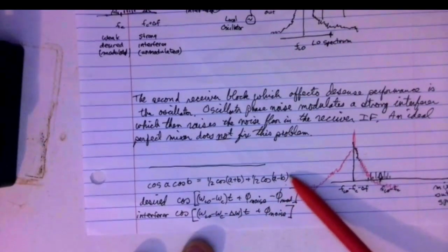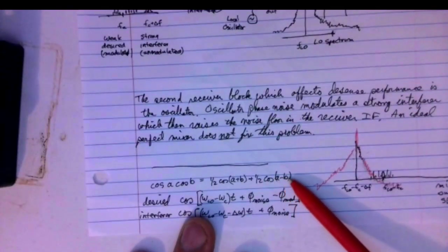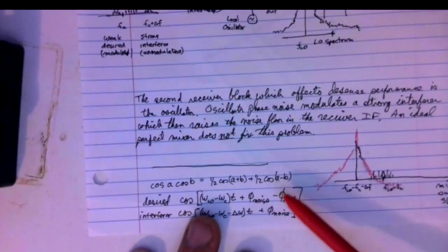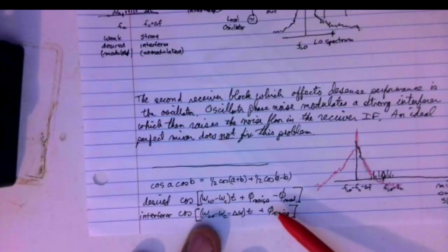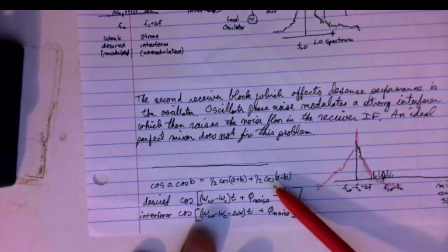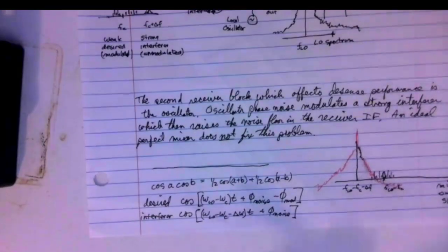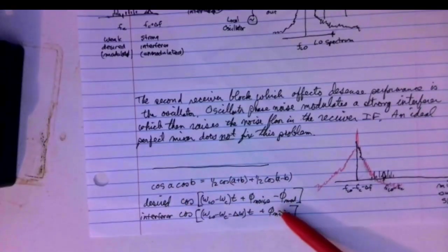Just the difference frequency here, and the difference frequency is generated by this term, and also the phase noise that's on the LO ends up on the difference, because it's not just the frequency that you take the difference of, it's that whole argument of the cosine here. Everything, phase noise included.